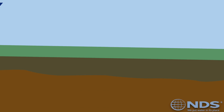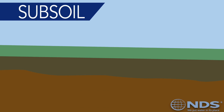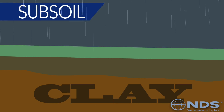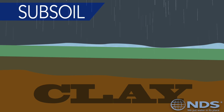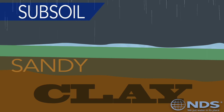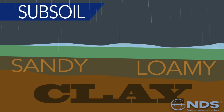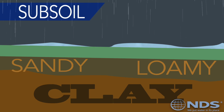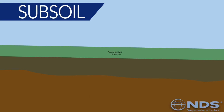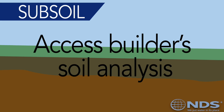Drainage is also affected by the subsoil. If there is a layer of clay a foot below the surface, for instance, it can prevent water percolation into the subsoil and can cause drainage problems on the surface, even if the surface level soil is sandy or loamy. This can be a problem on sites where soil has been imported to level the site or for landscaping purposes, covering a dense layer of clay on site before construction. When working with new construction, you might be able to access the builder's soil analysis for more thorough soil information.